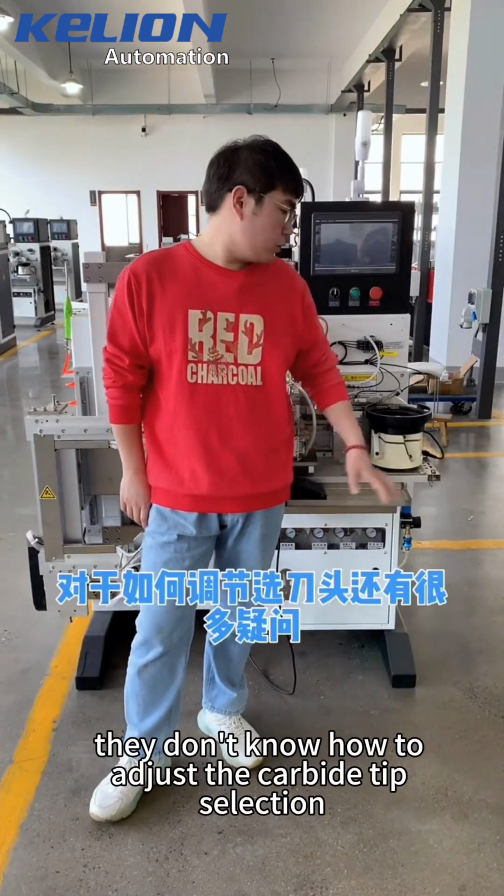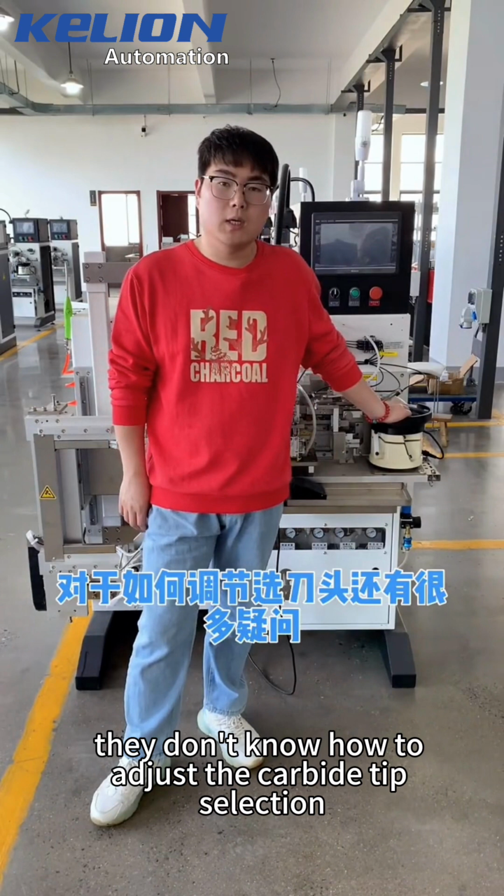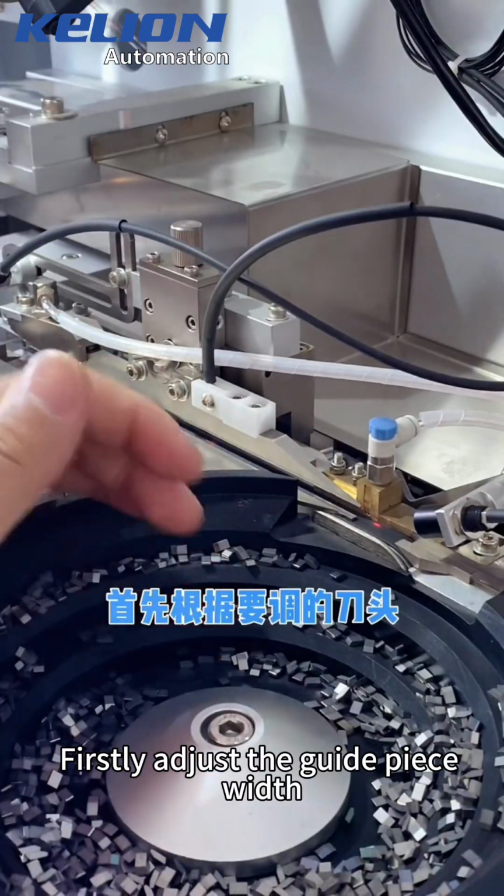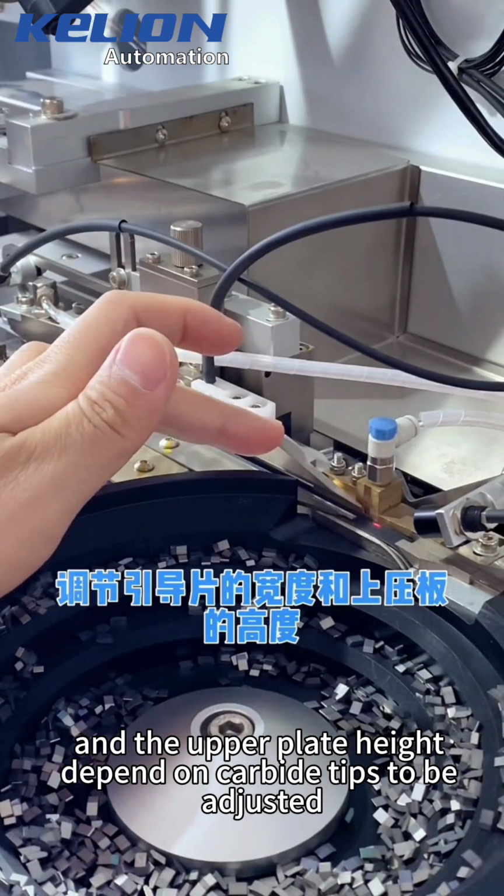Many customers said that they don't know how to adjust the carbide tip selection. Today, we will explain the adjustment procedure. Firstly, adjust the guide piece width and upper plate height depending on the carbide tips to be adjusted.